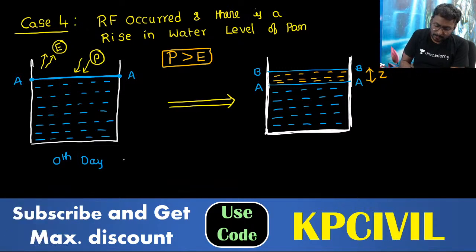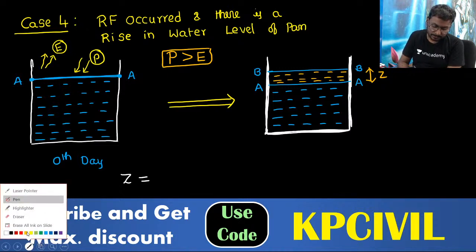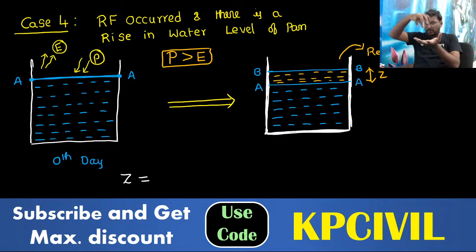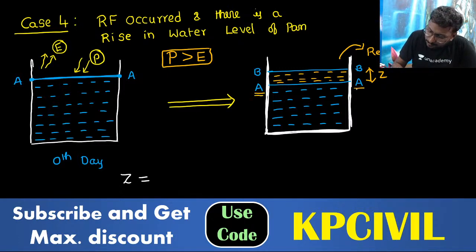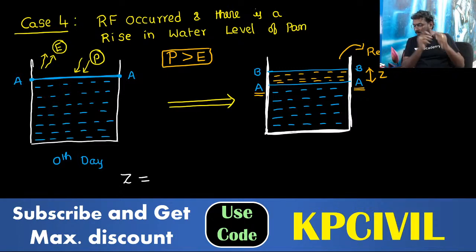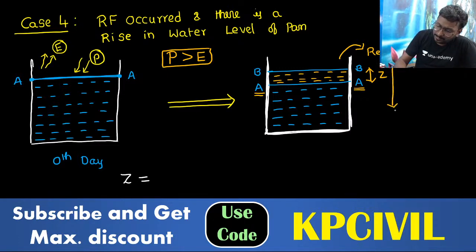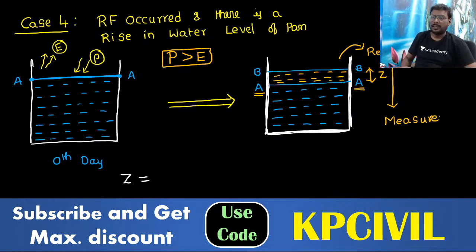Now how can you measure volume now? You are removing the water. Remove water and make the level up to A. Take out some quantity of water from the pan and make the quantity to be present up to A only. Remove water. Asif Hussain. Correct. Very good, Asif Hussain. Remove that excess water in evaporation pan, take it out and measure the volume of water removed.